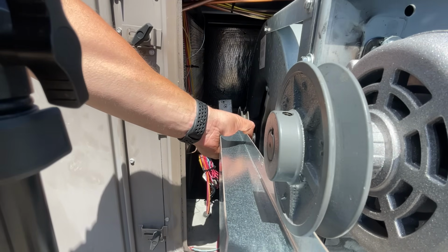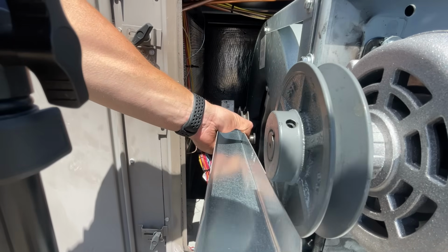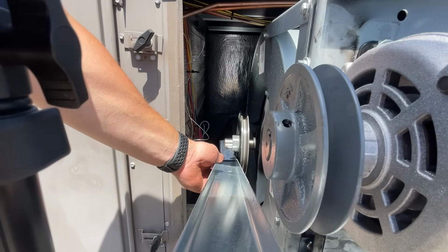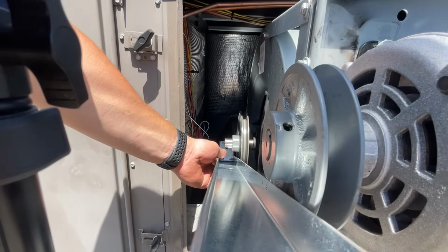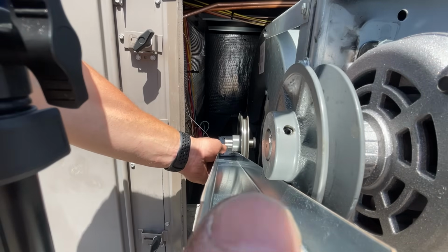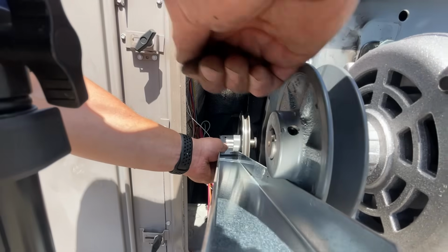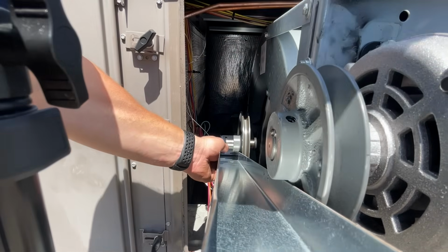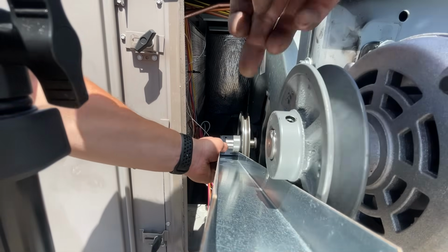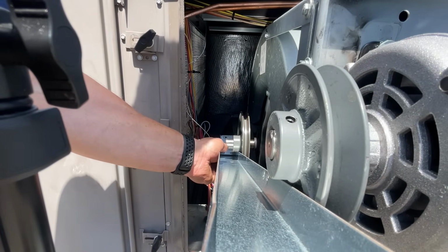So we're gonna have to adjust this pulley, push it back on the shaft a little bit until we get our 4-point contact. Just pushed our pulley back a little bit, and 1, 2, 3. So we don't have 4 yet. Let's push it back just a hair more. And there we go, guys. That's 4-point contact. We got contact here, here, there, and behind. So that's how we know we have a straight line.